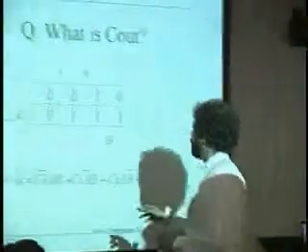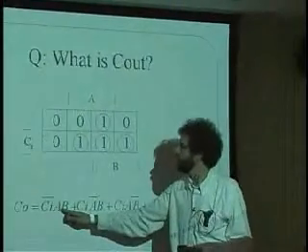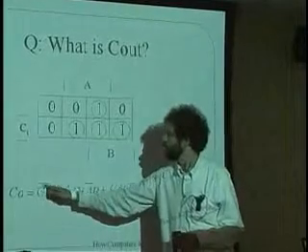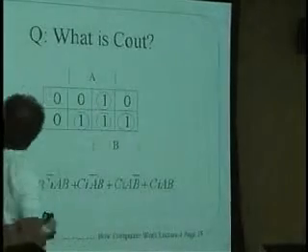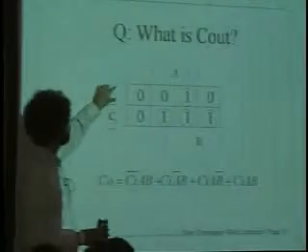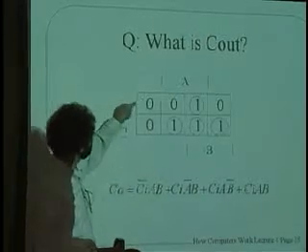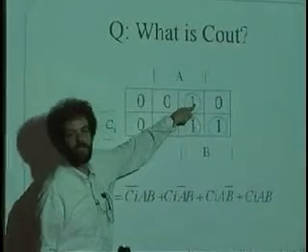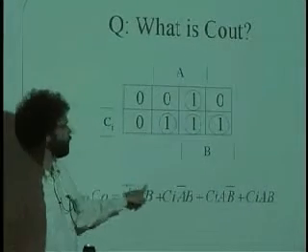So now let's look at a two-dimensional K-map with three input terms and understand the product terms. Here we have four product terms. Each of them has three inputs that it is sensitive to. C sub I bar A B. Now where is C sub I bar A B on this thing? C sub I is not true. That's up here. Here's the place where C sub I is true, here's the place where C sub I is not true. So C sub I bar, A should be true and B should be true. So we come along here. That one.